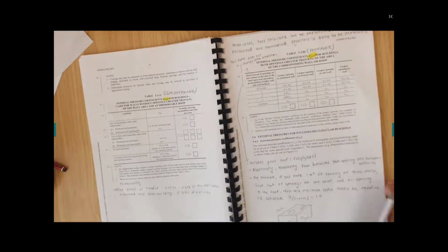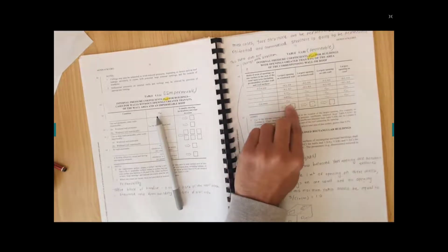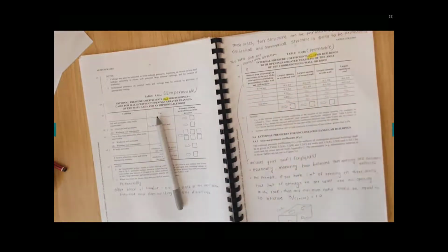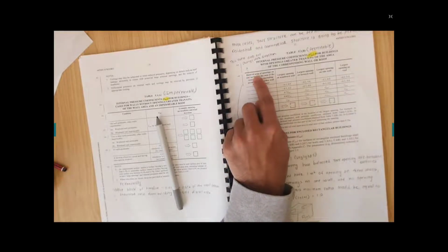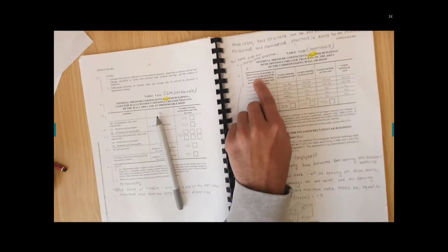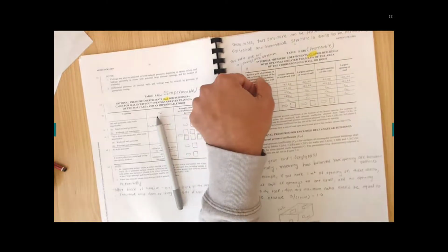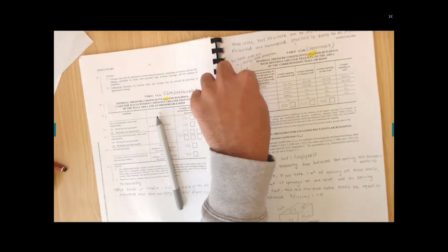When you have opening, dominant opening, like in our case where you want to think that someone wants to test your structures and they keep the door open on the windward wall and the wind is coming from that direction, straight away the wind will go inside and just try to inflate the structures. So in that case, we need to calculate this ratio of opening on one surface, that's in our case the windward wall, to the sum of total open area on the other walls.